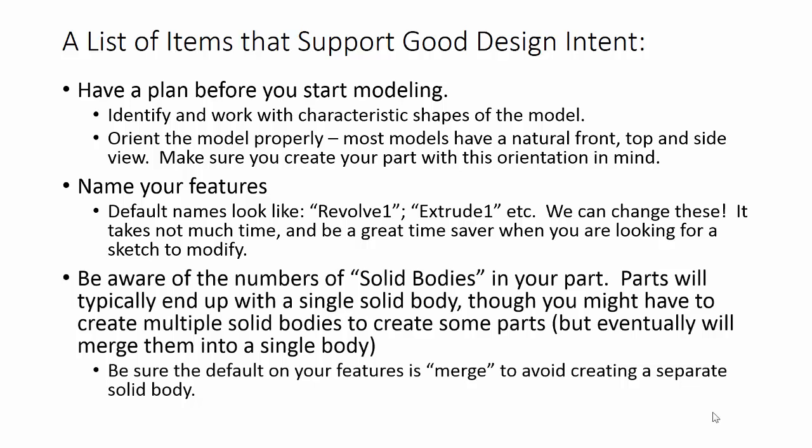We also want to be aware of the number of solid bodies in your parts. Sometimes we'll create parts that have multiple solid bodies. Usually they end up with a single solid body, so you might have to create multiple solid bodies as you're creating some parts and then eventually merge them into a single body. So we want to be sure the default on our features is to merge to avoid creating a separate solid body. I think that is the natural default, but if it's not, you could run into trouble.